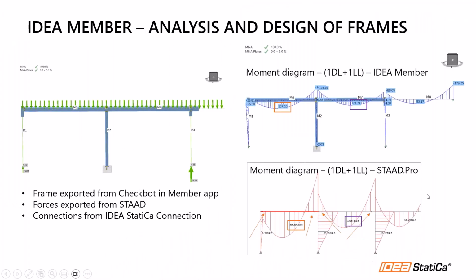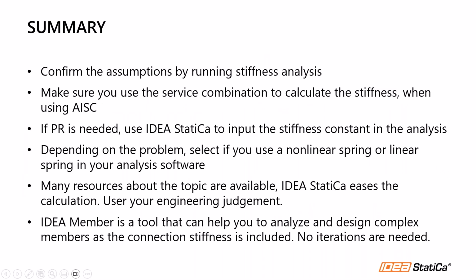All right, so what is the takeaway from here? By using IDEA Member, I didn't have to do this iteration between IDEA StatiCa Connection and IDEA Member. I just come here directly, model those members by importing them from Checkbot, run the analysis, and get the most accurate moment diagram and values. All right, let's jump into the summary of this webinar.